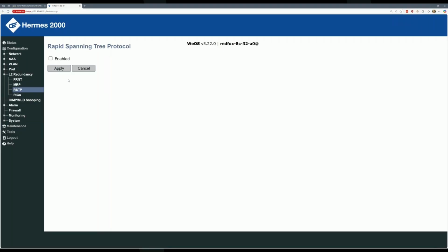It'll give you how to do it. But RSTP will have a couple of values. There's something called a distance. It's not like physical distance, but it's an idea of how far in your spanning tree, how many, you might call it hops, you have to go to get somewhere. And so you can configure your spanning tree with pre-configured distances. And there's a whole thing of how quickly the network can recover. Spanning tree, though, takes several seconds, whereas your 61850 based protocols, HSR, PRP can go much, much faster, which is desirable.